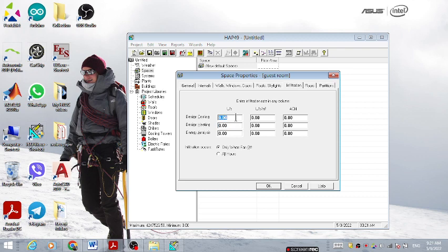The rate is in liters per second. There are several methods. People times 5.25 times 3... You have to review my lecture about infiltration and ventilation needed. The volume will be about 78 cubic meters, times 2, assuming 2 air replacements due to air infiltration, divided by 3,600 seconds. So it will be times 1,000. It's about 43 liters per second. Let's say 43 for heating as well.